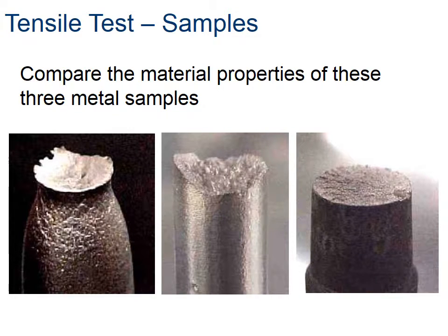Well, here are some actual photographs, and what's different is that on the left side you can see some necking, as opposed to the right side, where it almost looks like a clean break. The major difference here is brittleness. On the left-hand side I have something that's pretty stretchy, and on the right something that's a lot more brittle. I don't know what material it is, but it might be like a ceramic. And on the left side, this is going to be a softer type material. And then, of course, there is everything in between.